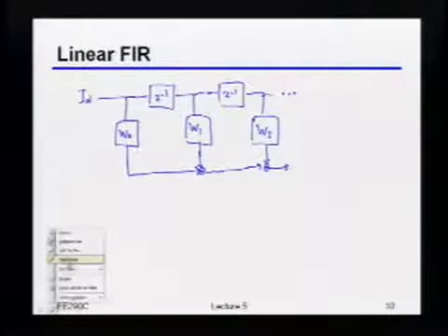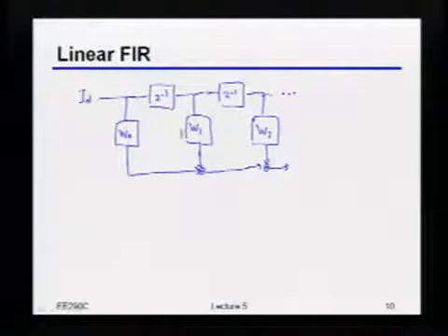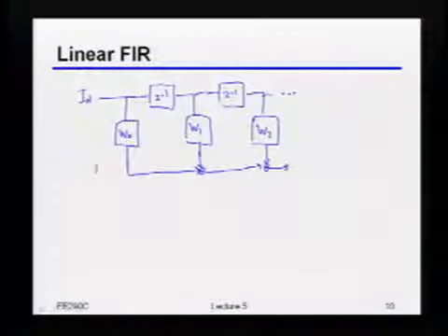Okay, so just from a terminology standpoint, since I'll probably say it and may forget to define it later, each one of these coefficients is usually referred to as a tap, because it's kind of like a tap off of this delay line. So this would be, for example, a 3-tap FIR filter. Now, I'll talk a little bit more in a second about where or how you'd implement this, but let's assume that you can implement this one way or another.